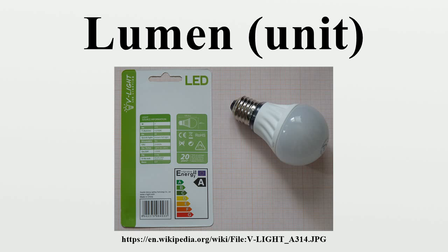The method for measuring ANSI lumens is defined in the IT7.215 document, which was created in 1992. First, the projector is set up to display an image in a room at a temperature of 25 degrees Celsius. The brightness and contrast of the projector are adjusted so that on a full white field, it is possible to distinguish between a 5% screen area block of 95% peak white, and two identically sized 100% and 90% peak white boxes at the center of the white field.